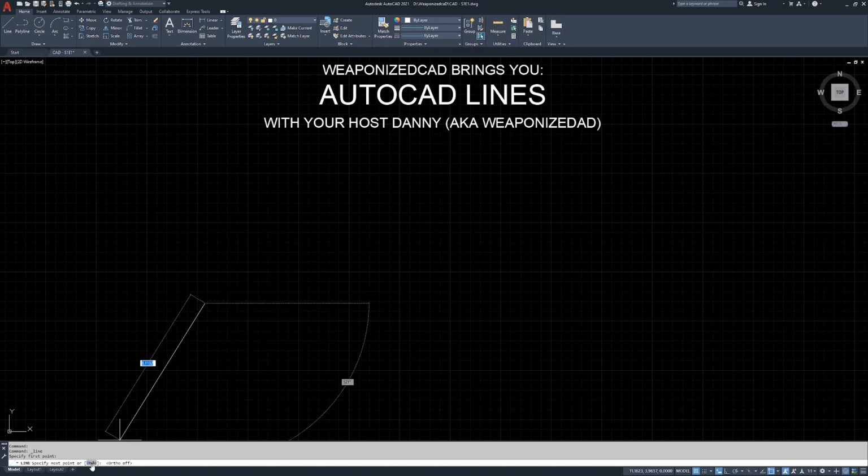You'll notice that undo is shaded. That means that you can either type U, enter, or click it, which is highlighted blue. I'm not sure if you guys are going to be able to see it. In these later versions of AutoCAD, they actually made these buttons down here clickable. So every so often you're going to run into a command that has a series of subcommands. Undo is going to undo back as far as you want, really. You can click the undo command and get all the way back to the point that we're at right now. It's not going to undo you out of the command. It's only going to undo any line segments you've drawn all the way back to the starting point here.